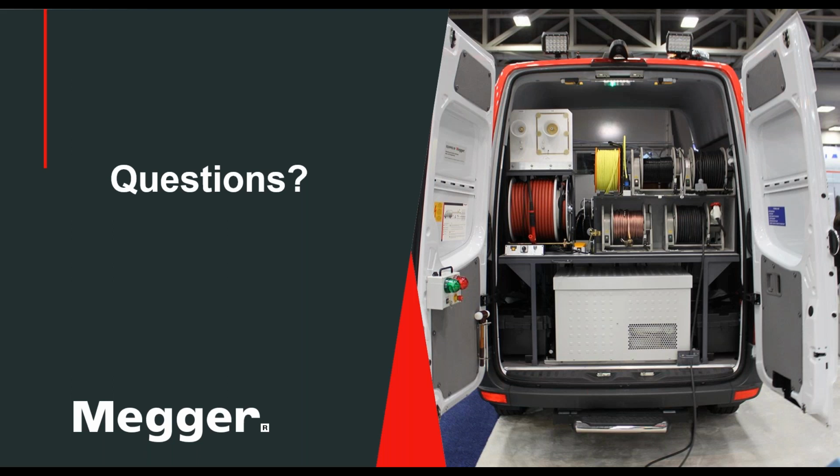I may not understand this question correctly, but what we're going to do is a breakdown test that tells us how much voltage we need to use. And of course, we can control the voltage output of our thumper. So the joules are going to be a result of the thumper we've chosen, because it has a set of capacitors in it, and the voltage level.